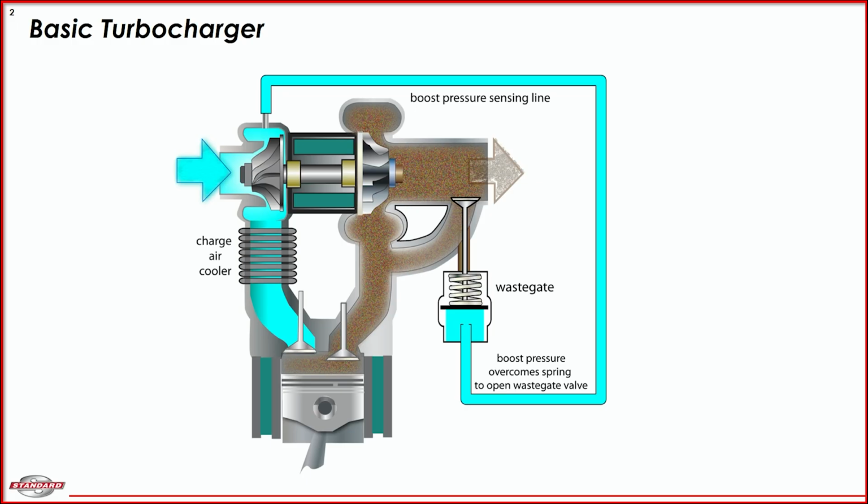And that's going to connect the turbine and compressor wheels together. So it's really just three major components there. And then that turbine wheel is going to be responsible for converting heat and pressure into rotational force. We've got the high pressure from the exhaust manifold that's always going to seek low pressure. And as the exhaust exits the cylinders and flows to the exhaust, it's going to spin that turbine and convert kinetic energy into rotation. And as that turbine wheel rotates, it of course is then going to spin up the turbine shaft, which is in turn going to spin up the compressor wheel.